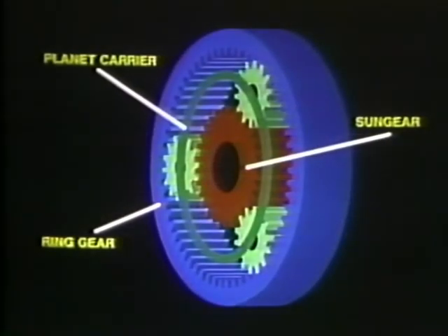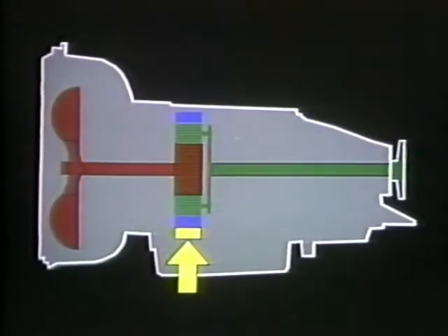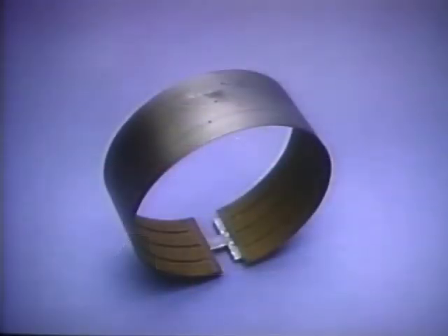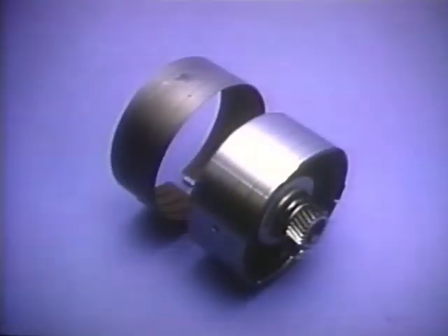As we have explained, engaging gears in an automatic transmission is actually the process of controlling the operation of the planetary gear sets. Now let's see how this is actually accomplished. First, we will look at how one component is physically locked in place so that it cannot rotate. There are three major components which accomplish this. The first, as shown here, is called a brake band. The second component is called the brake band drum. The drum is attached to the part of the planetary gear set which is to be held in place.